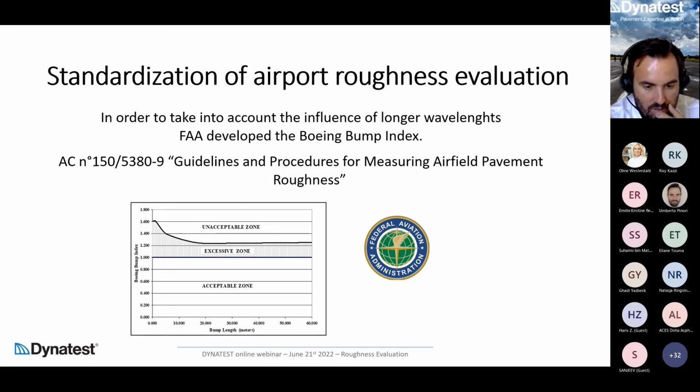Ideally, we operate between 30 and 100 km per hour, with a standard speed of 80 km per hour. If we capture and measure at 5 meter interval with 3 cameras, we try. Oh, yeah, it's good. So you have experience. Anyway, 80 km per hour is a reference, or 40 km per hour sometimes is a reference also for the algorithm in calculation. Of course, it's very hard to drive at constant speed. The more constant the speed, the better the survey. But of course, the algorithm in post-processing simulates a proper speed of calculation.